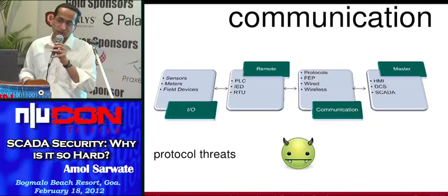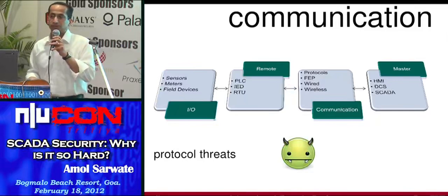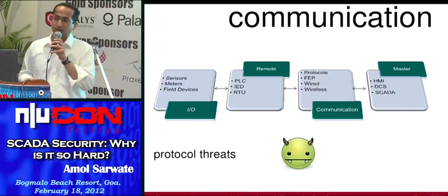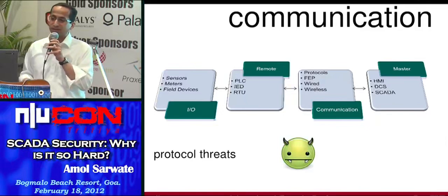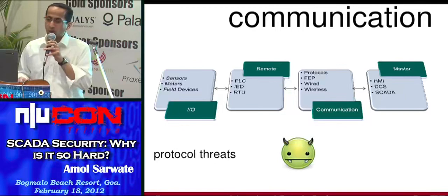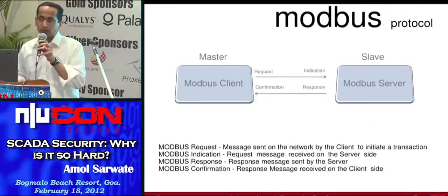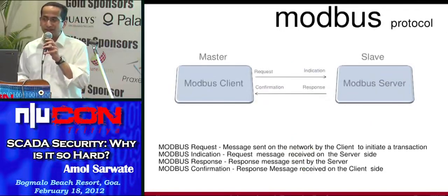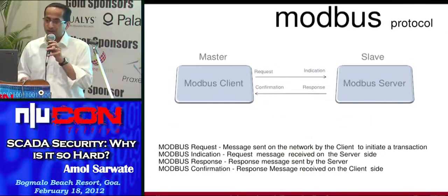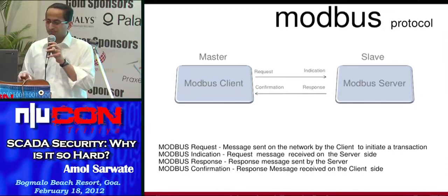And now we come to more of a juicy part, or the part which is more interesting, is there are a lot of protocol-based threats in the protocols that are used for SCADA communication. One of such protocols that we will look a little bit into detail today is Modbus. It's a very simple client-server protocol used in SCADA.